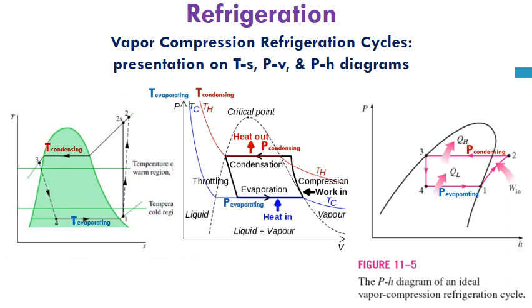The third process is from state 2 to state 3 inside the condenser. Started from desuperheating from point 2 until reaching the HG at condenser pressure on the vapor saturation line, then starting to condense the refrigerant inside the condenser until it reaches state number 3 at the liquid saturation line, which is equal to state number 4 in the enthalpy.